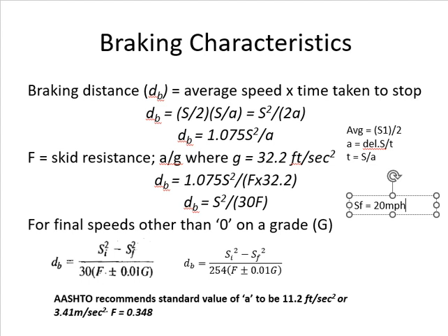And what is the braking distance? We have to do it twice because we have two different surfaces. If it was the same surface, we would take 175. But now we have shoulder different and pavement different. What will come first here? Shoulder, because we have the final speed which is at the shoulder. So we have to find out the initial speed at the shoulder. So at the shoulder, my braking distance is 75 feet and the F value is 0.25.